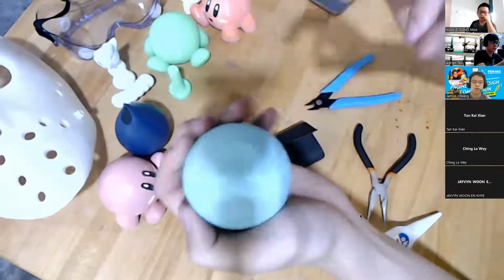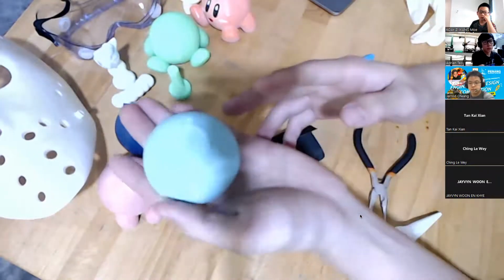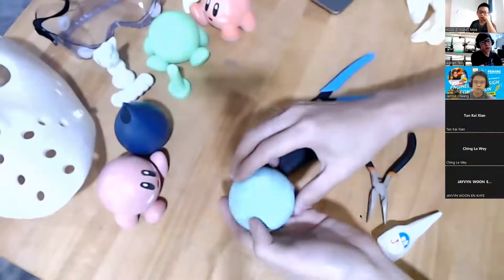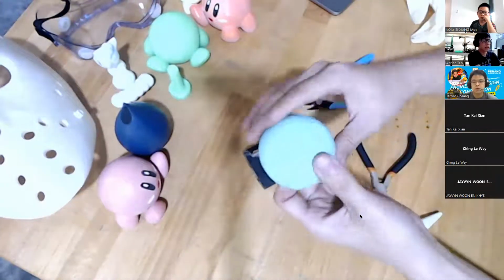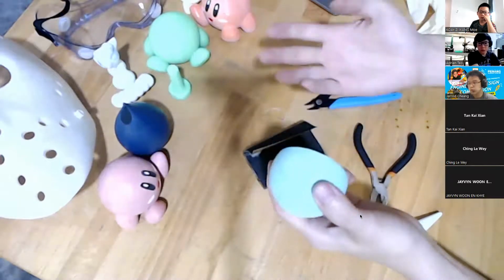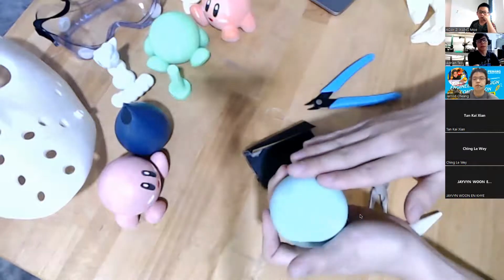1,000. Okay, so after you sand, bring your part and soak it into water. You can wash it with soap water too. Wash it and then dry it, rinse it, dry it. And then after that, continue with sanding a higher grit sandpaper.